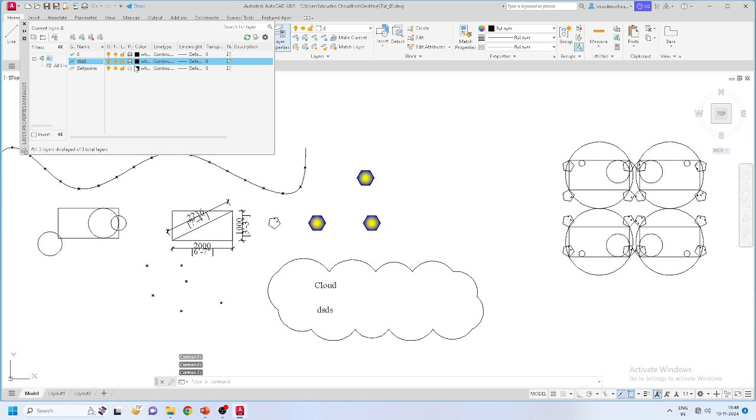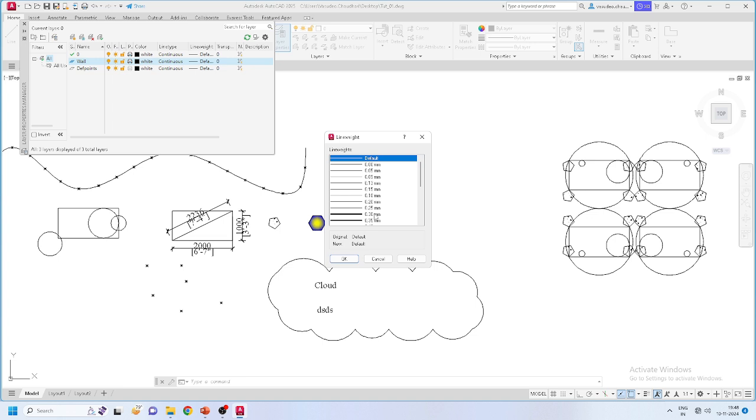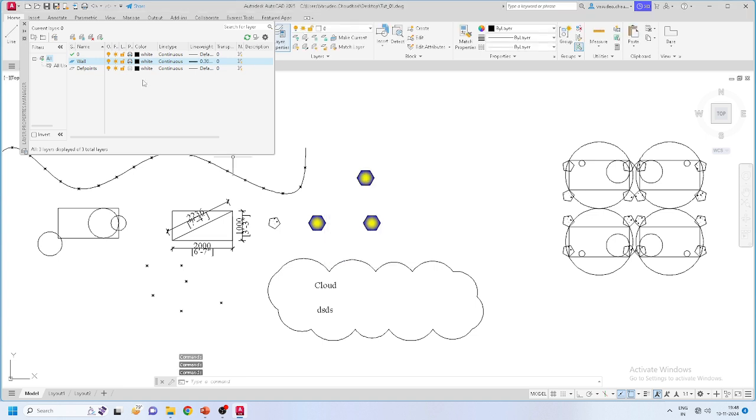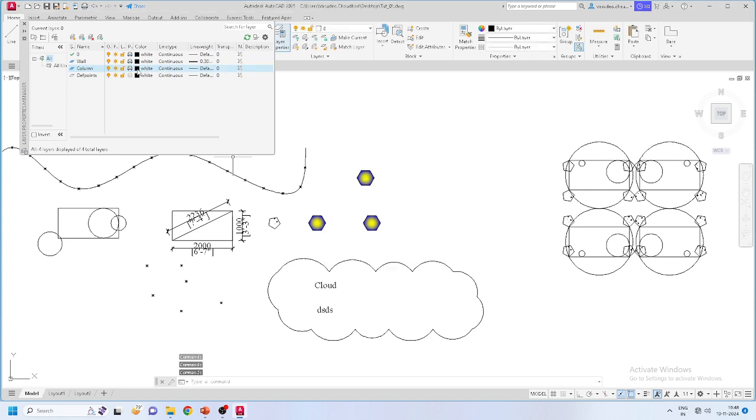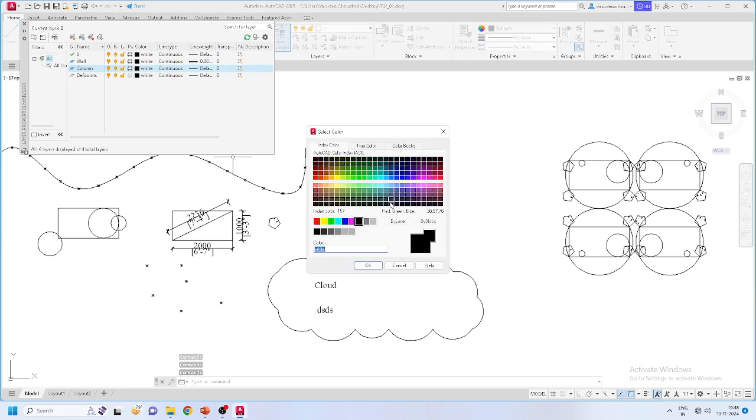Now by default black and white color is selected here. Again the type of line, continuous line, I'm using. The line width I'm selecting a little thicker, so let's assume that is 0.3 thick. So that I have selected. Then next I wish to show columns also, column. So I have selected column. Maybe this I don't need that thick, so let it be that thick only. But the column I wish to show with a different color, so I'm using red color to show the